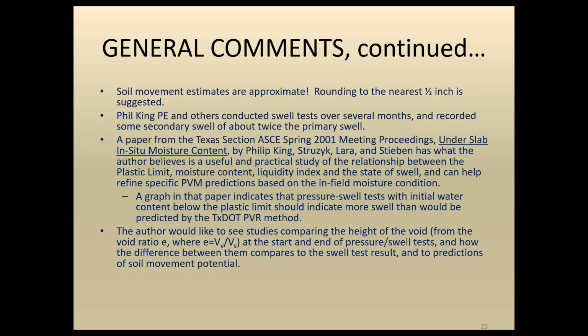That paper contains a graph that would indicate that the pressure swell tests with initial water content below the plastic limit, like we're advising be done and we do in our procedure, should indicate more swell than would be predicted by the TxDOT PVR method, because as you saw in the program for the PVR method, it assumes an initial dry state of about the plastic limit.